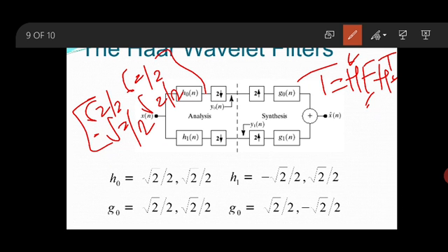That is what you can see in the block diagram also. If I consider x[n] as the image, H0 will have a coefficient root 2 divided by 2, and H1 will have a coefficient here. You can see there is a down arrow, meaning you are performing down sampling on the operations. How long will you perform this? Until you reach level J, one level at a time.